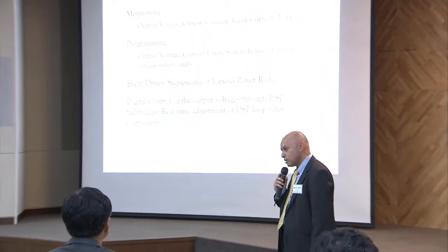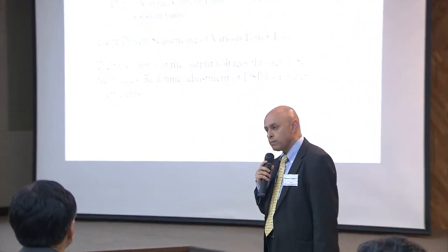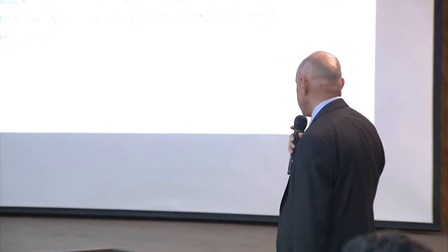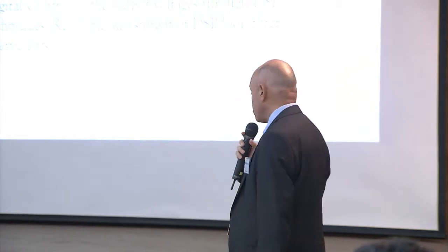Now, what do we use the digital power for? There's multiple uses for it. First is monitoring. Monitoring things like output voltage, output current, different temperatures around the board, and basically fault monitoring, monitoring the different faults within a system. So we need a communication bus to monitor all these faults.